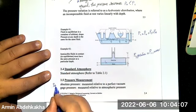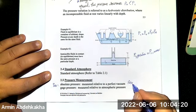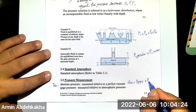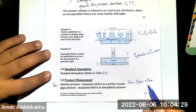So P absolute is measured relative to a perfect vacuum. Perfect vacuum means that the atmospheric pressure is also added. So P absolute is P gauge plus P atmospheric. These two are summed together.